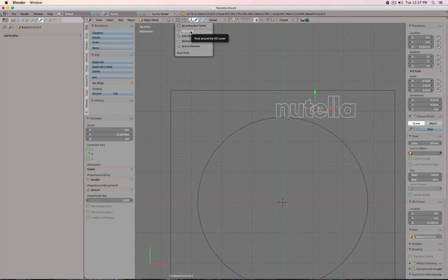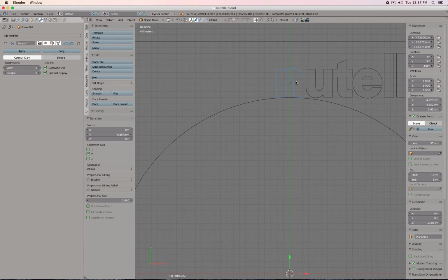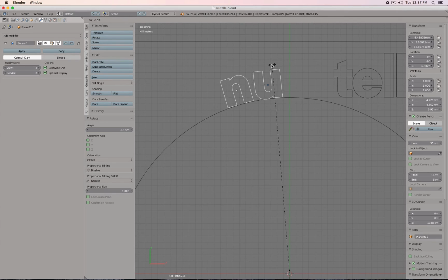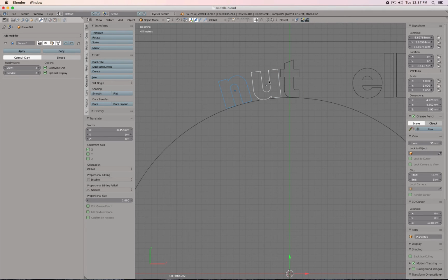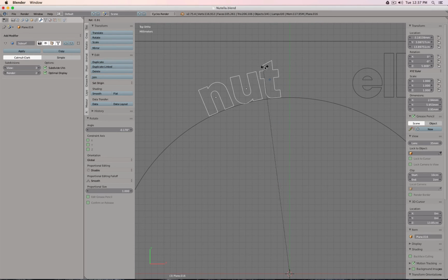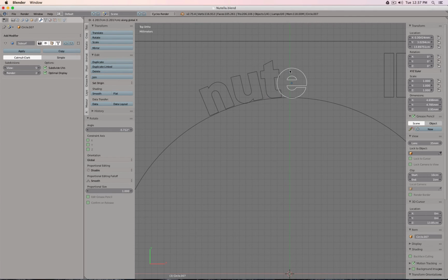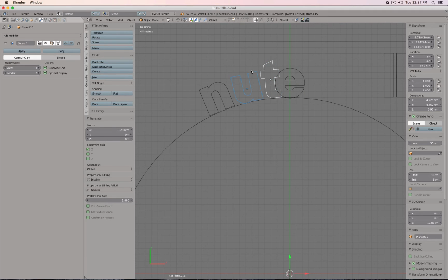I set the 3D cursor and then, for example, select N and simply rotate it. And I select this one, G and X to there. There, see, now this has to rotate a tick more. And then I rotate G and X till it's centered. This is a little bit too tight, so R, there. The E is pretty wide, so I might need some extra space here.